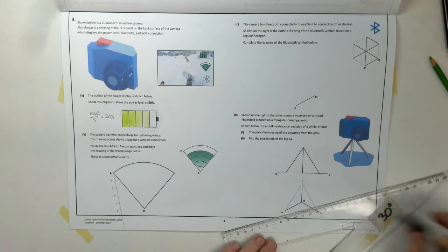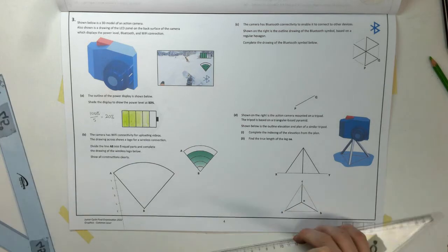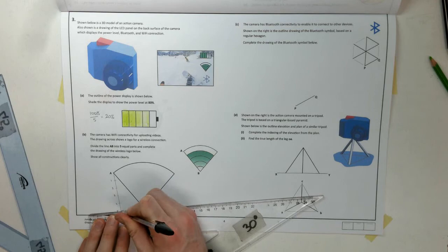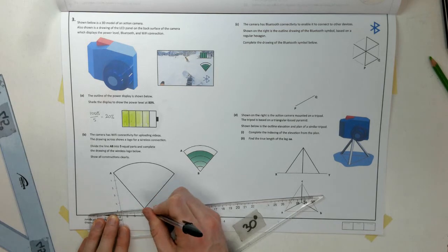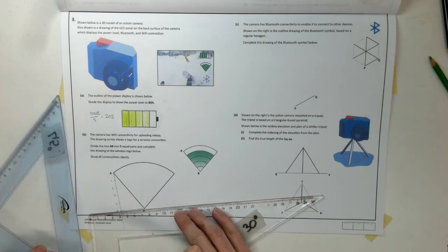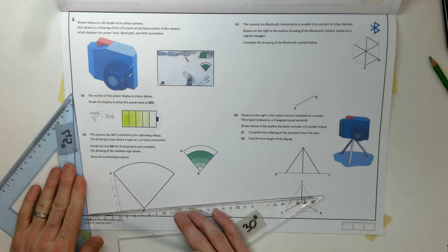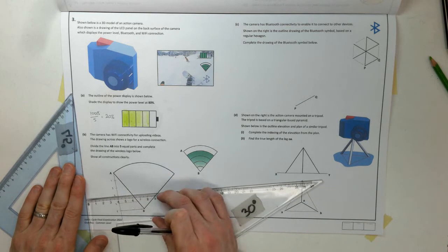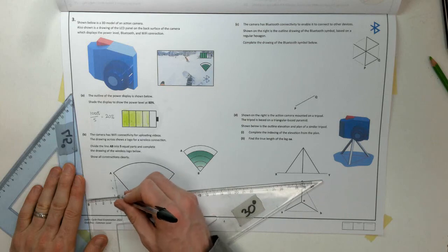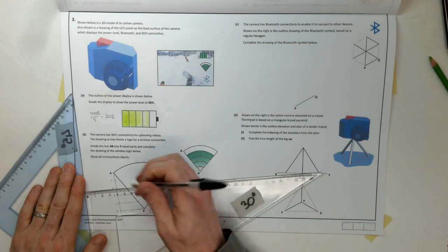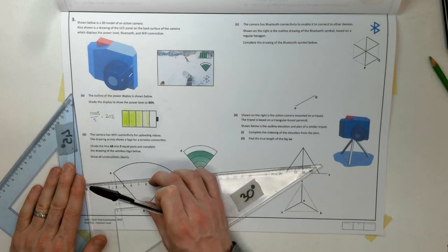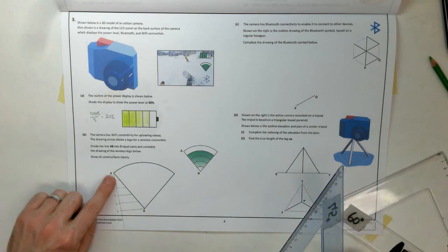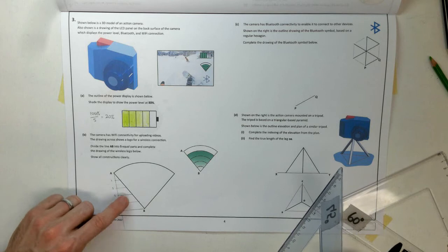So that's great. Now the important line is joining that final point back to B, because now I'm going to use sliding set squares to draw parallel lines from each of my other points. Okay, so I've divided line AB now into 1, 2, 3, 4, 5 parts.